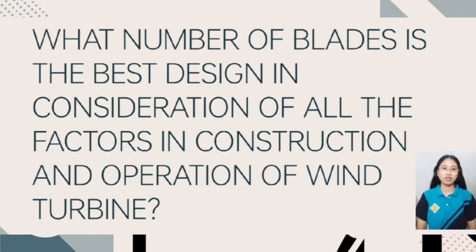Being an engineer, what should be considered to ensure the highest level of efficiency? Engineers must consider speed and drag in designing the blades. For example, if too much drag is created by the obstruction of the blades, the power yield will be a lot lower. If not enough drag is created, the blades could move too quickly, causing them to break the sound barrier. In summary, in designing the blades, the one that should be minimized is the drag force, and the one to be maximized is the lift force.